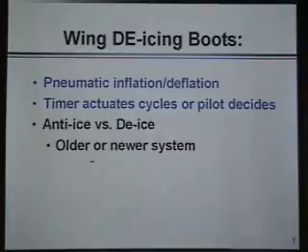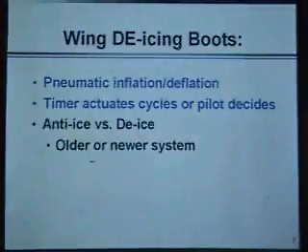If it's a post-1970 set of pneumatic wing de-icing boots, the boots inflate and deflate very rapidly, and it'll break off the ice as it's forming, so you don't have to wait until the ice forms. Now, that's typically the way you want to do it, but if you happen to leave the old-style boots on inadvertently, you're going to get ice forming around the outside deflation area, and it's not going to end up cracking. On the newer systems, if you happen to leave it on, it would still anti-ice.